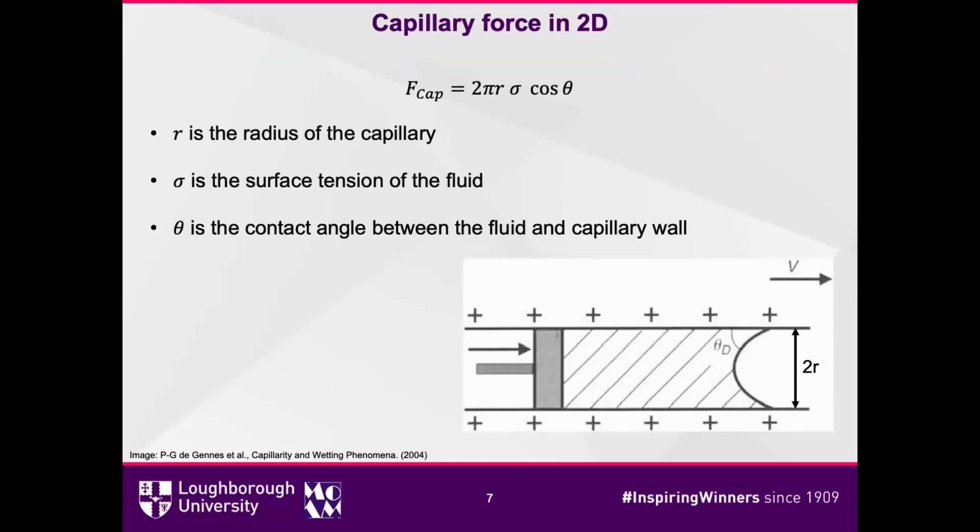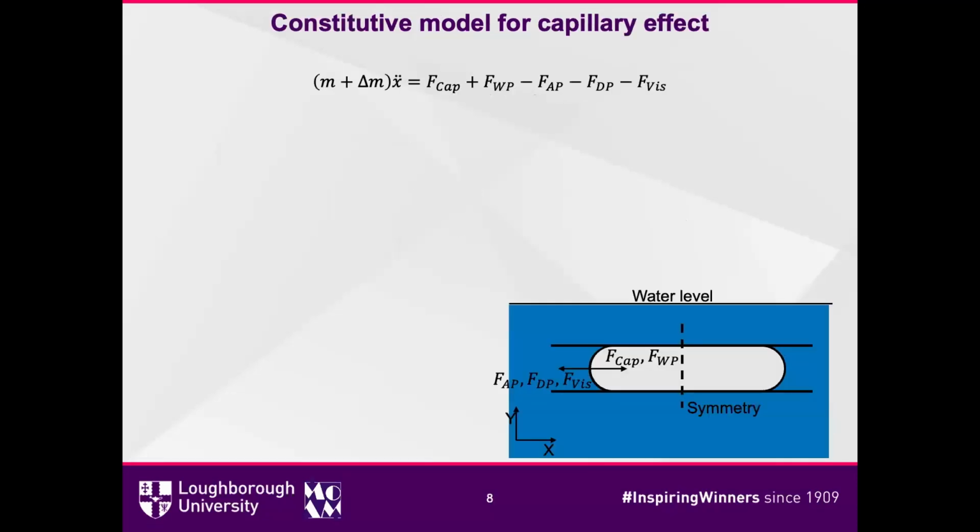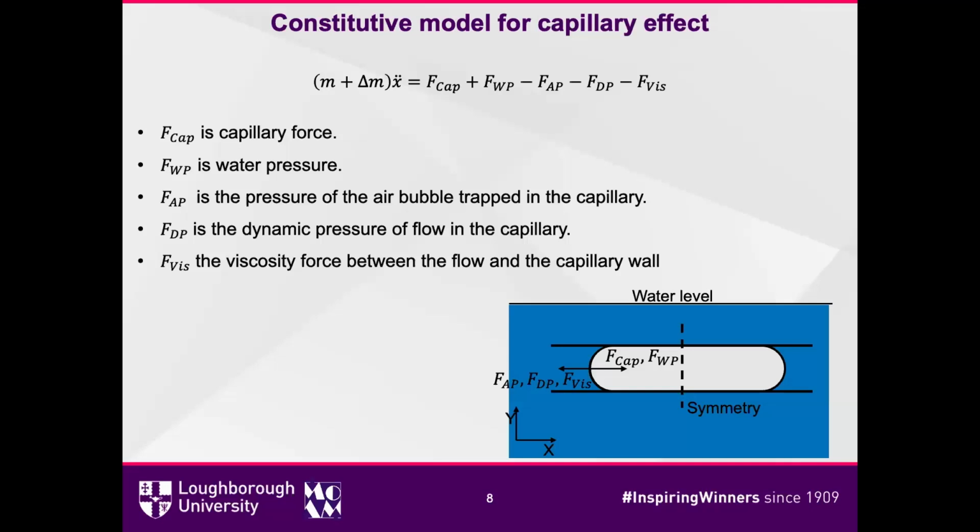This is the basic rule of the capillary force in 2D, and I'm going to use it in my later research. This is the constitutive model of the capillary effect. As we see, the capillary effect and the water pressure push the water into the capillary, while the air trapped inside the capillary, the dynamic pressure and the viscosity forces are the forces that retard the water flow into the capillary.